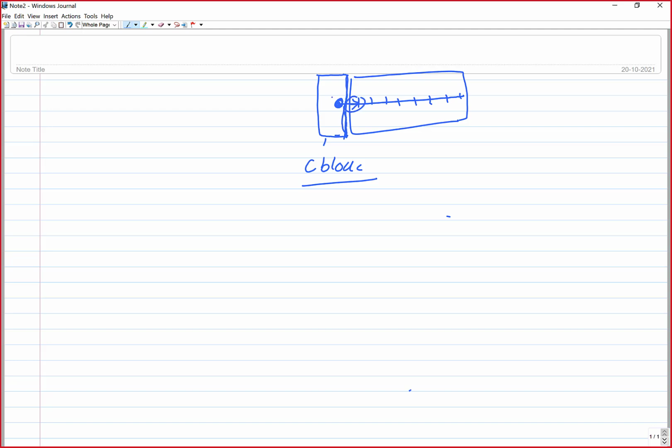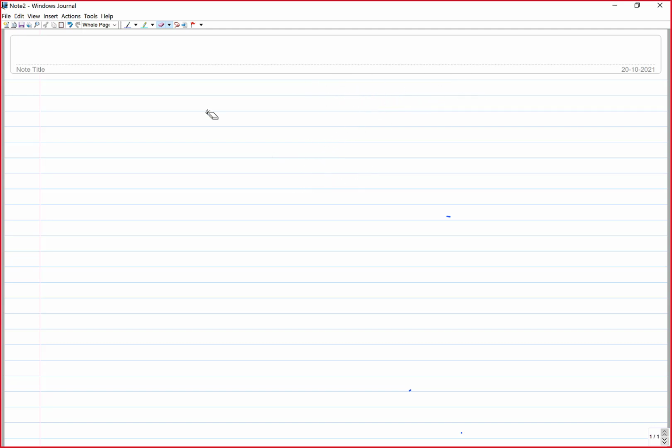The advantage of this method is that you directly supply the heat to the workpiece, and there is no striking of the arc here and there on the base metal, but the arc is initiated on the carbon block itself. So this is the third method, you can say. It is just a variant of the touch start method, because in any case we have to touch the carbon block using the electrode.